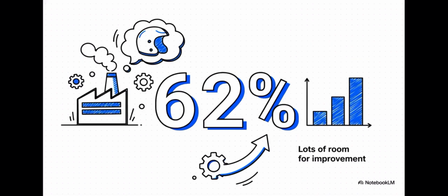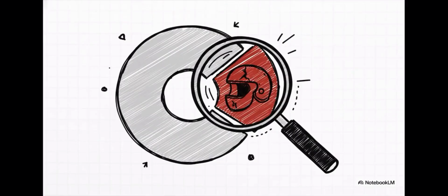Here's another great example. A company called PT Polyprima, they make helmet shells. They started out with an OEE of 62%. You know, that's that pretty average score we talked about. Not bad, but definitely has a ton of room to grow. So they did their homework, they ran the numbers, and the data pointed to one main culprit: process defects. Basically, they were just making too many bad parts during a normal run. That one issue was responsible for 18% of their entire loss.